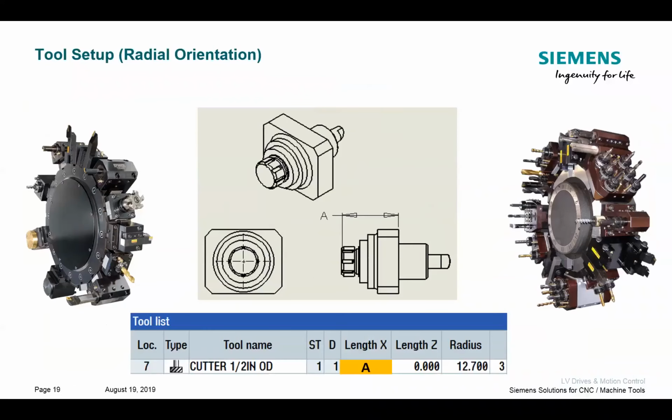Now, as far as from a tooling perspective, generally most of these turrets were established on a known datum to that spindle face. So it's not uncommon at all for the center line of the live tools, especially any of the live tools pointing down towards the, in the x-axis direction, that center line would be Z0. So if I sent the turret all the way to machine 0, it would be dead center of that turret face. And then from there, if I'm just working off that tool, I don't need to necessarily put a Z offset as long as the center line of that spindle is on the center line of the turret. So then I just give it an offset projection in my X to compensate.